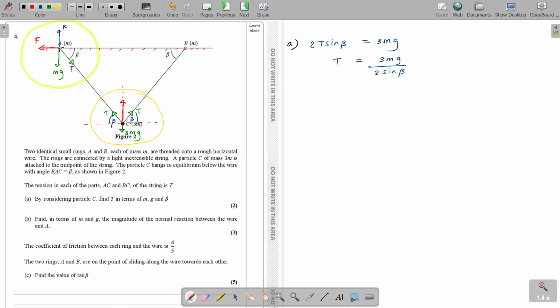The first thing. So what happens when you resolve the tension? Towards the angle you get T cos beta, away from the angle downwards, can you see, you get T sin beta. I marked it downwards because it acts along the direction of mg downwards. So mg plus T sin beta, because T sin beta comes down. When you resolve away from the angle, the arrow is pointed down. Okay, so now I don't need to work with this tension, so I can work with the horizontal and vertical equilibrium. So now what do we do?